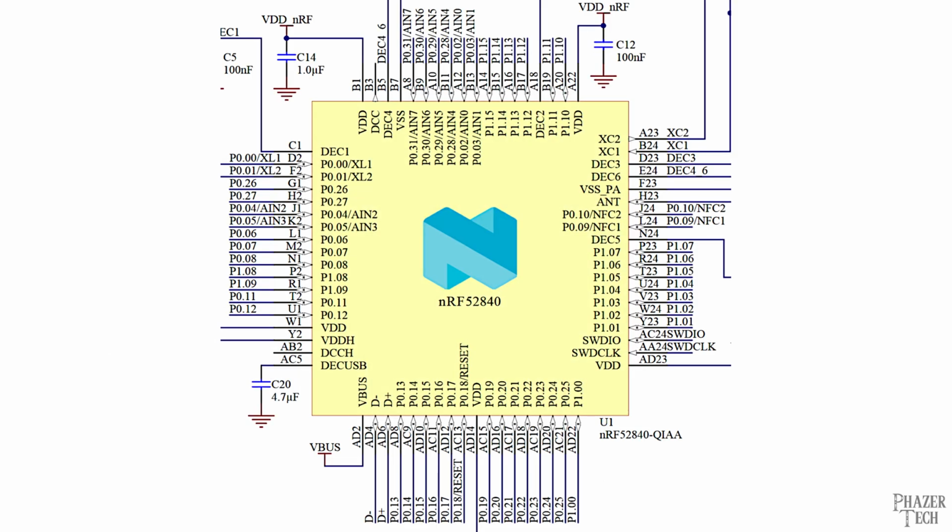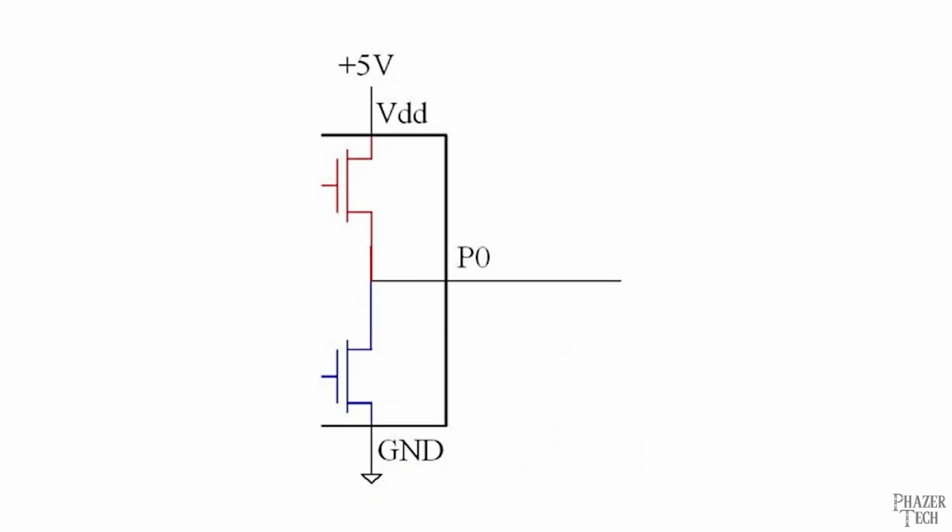Microcontrollers contain a number of input and output pins, and the output pins can be used to control other devices. It turns out the output pins are actually tiny transistors themselves, but most of them are only capable of outputting up to 5 volts, and each pin is only capable of supplying up to around 10 or 20 milliamps, depending on the particular microcontroller.